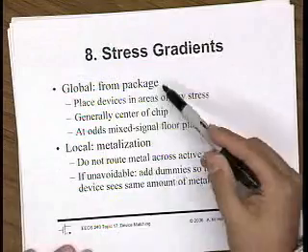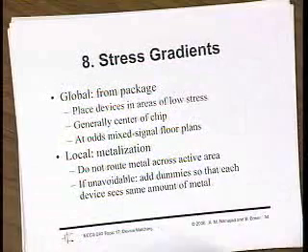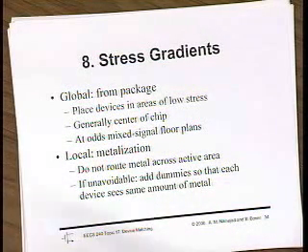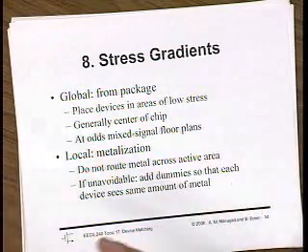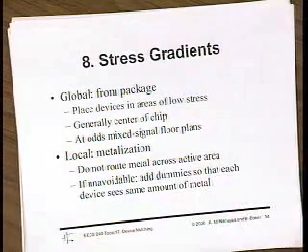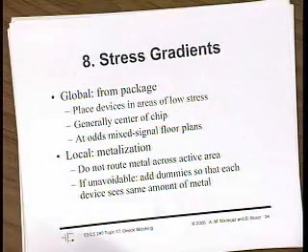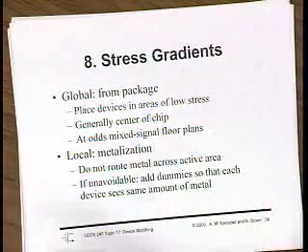And so things like, you wouldn't expect, stress from the package, just the fact that the edges of your device have bond wires going to them or solder bumps going to them, they have different stress than the center of the device. So the center is probably the best place if you want to avoid stress. If you can't avoid it, this is what I was going to say earlier, you use common centroid layout, because the stress, again, is some kind of gradient across your chip, and by proper layout you can minimize its impact.